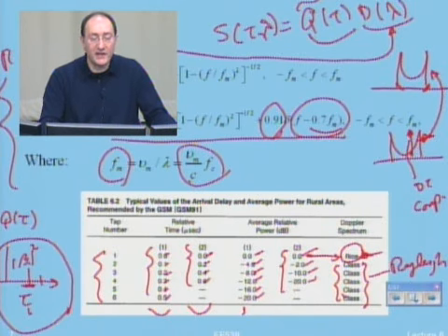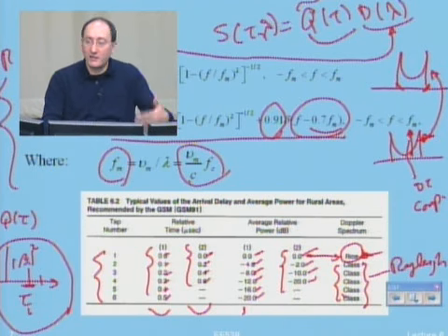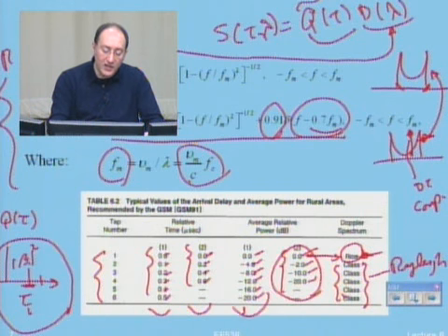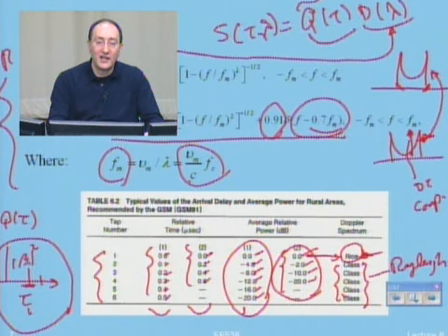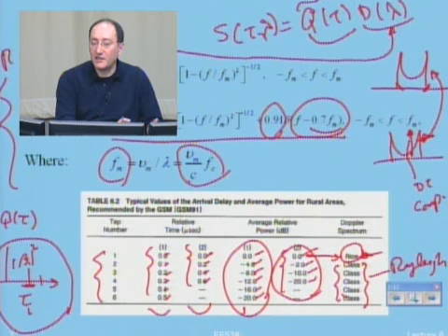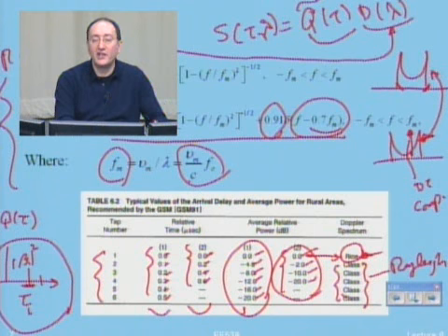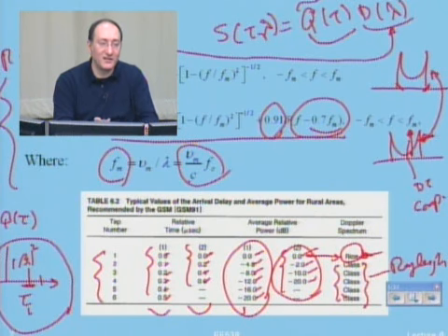Okay? So basically the same Jake model that we had for simulation, where we had filtered Gaussian noise, I will do several of them, either 4 of them or 6 of them, and I add them at different delays. How do I create the delay in MATLAB? That's very easy. That's mathematical. How do I create the delay with hardware? I put a D flip-flop or a delay line between different paths.